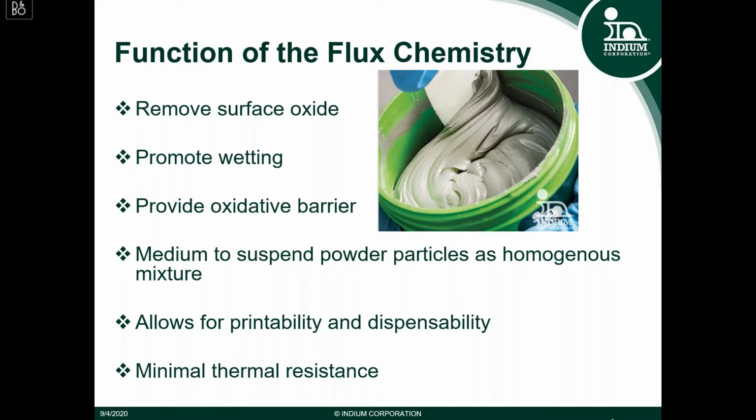You need to remove the oxide layer because it helps to promote wetting. It helps to make sure that the solder is wetting to your surface properly. The flux also provides an oxidative barrier, preventing further oxidation from occurring during the reflow step.